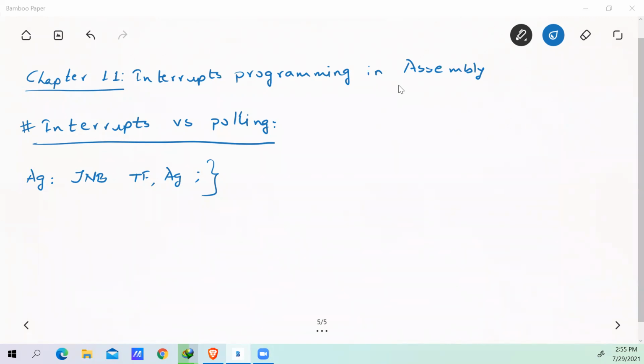Sir, polling. Sir, interrupt. Okay, someone said interrupt, someone said polling. Let's share the logic. Whoever said polling, why do you think it is polling? Sir, it is continuously checking the value of the overflow flag. Until a specific time, the overflow flag becomes 1, it reaches back to its restart value. So I guess it will be polling, sir, because of this.